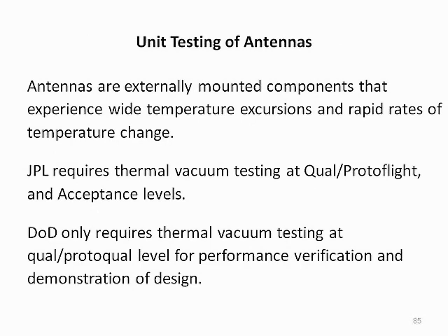Antennas experience wide temperature excursions and rapid rates of temperature change because they are low mass and have high surface area, directly exposed to external space environments. JPL requires thermal vacuum testing at the qualification or protoflight level and at the acceptance level. DoD requires thermal vacuum testing at qualification or proto-qualification level only for performance verification and design demonstration.